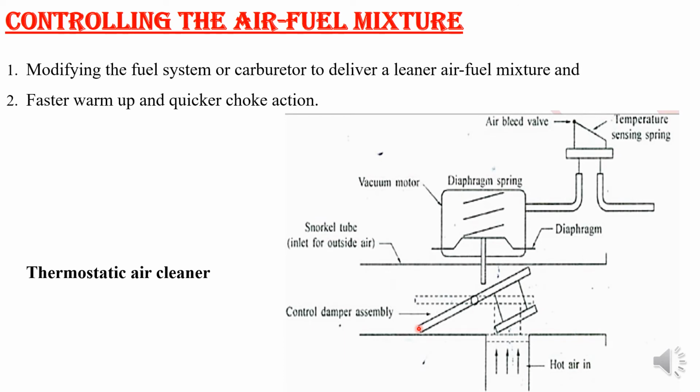of oxygen is in excess. So as the engine mostly runs at part throttle, this electronic circuit module will maintain the air fuel ratio near to the stoichiometric during the part throttling. Engine performance is better at the ideal air fuel mixture and produces minimum exhaust, and the amount of oxygen in the exhaust is indicated by the oxygen sensor, which sends a signal to the ECM. So this shows the leanness or richness of the air fuel mixture. So the ECM will adjust, that is the electronic control module.